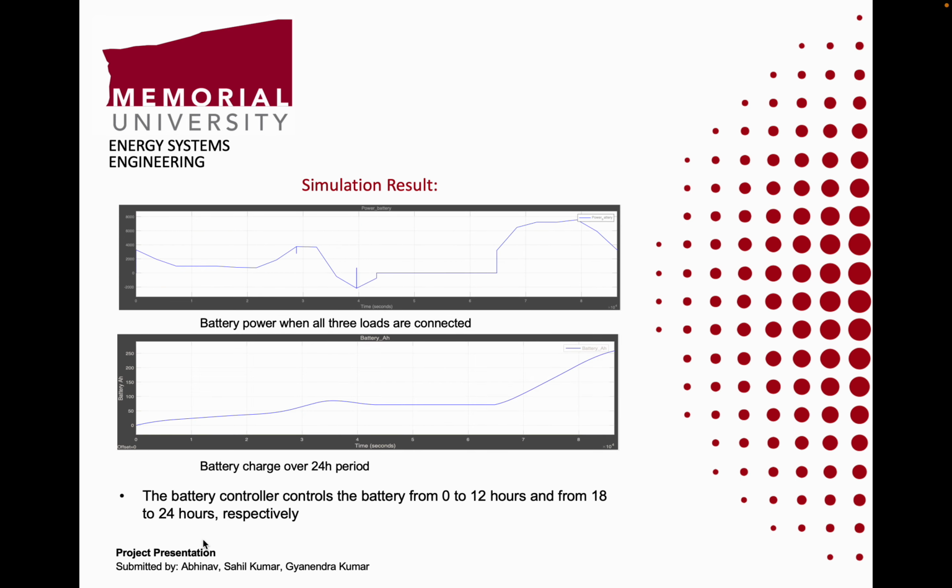And from the next two simulations, from 12 hour to 18 hour, the battery control is not performed. So the SOC, the state of charge of the storage battery, is fixed to a constant and does not change, since the charge or discharge of the storage battery is not performed by the battery controller. When there is a power shortage in the microgrid, the system power supplies the insufficient power. When there is a surplus power in the microgrid, the surplus power is returned to the system power.